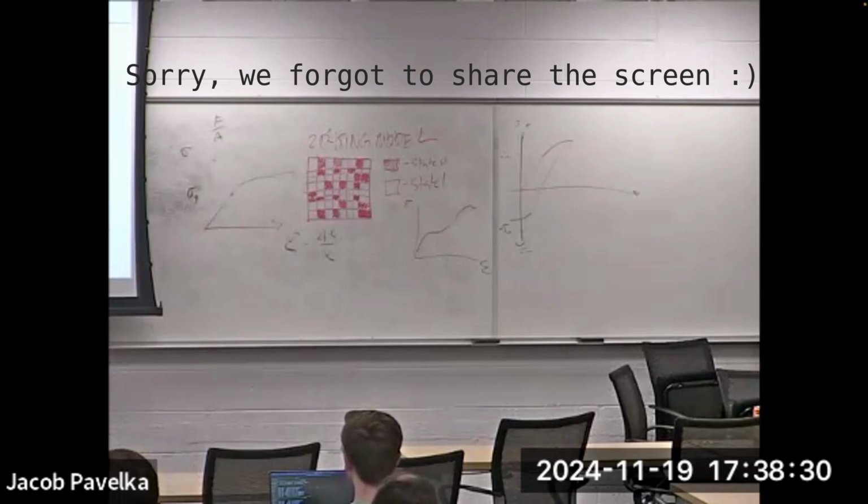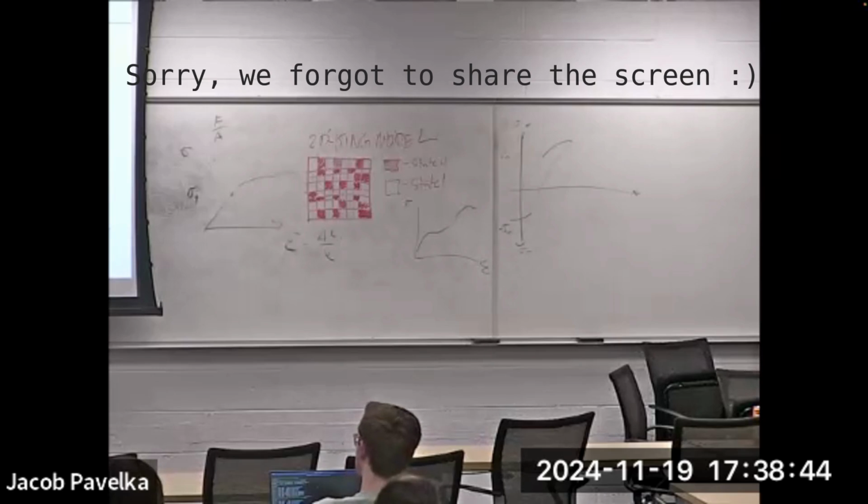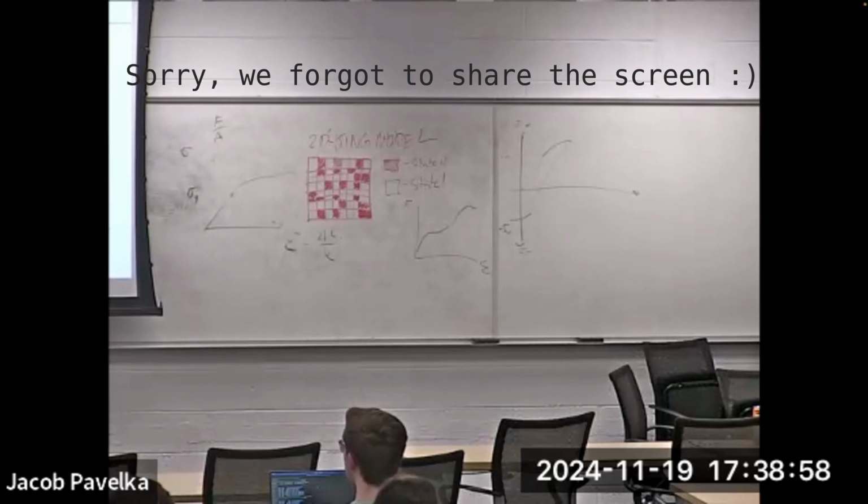So just to illustrate this, I had my terminal open already. This is what I was talking about, and I'm going to show you guys how to look at this output, at least on Great Lakes. And if you run it on the PRISMS toolbox, it'll just print this out to your terminal as well. But here I'm doing 16 nonlinear iterations, and my residual has kind of plateaued. It's not going down anymore. I don't think anyone in this room knows the reason for that.